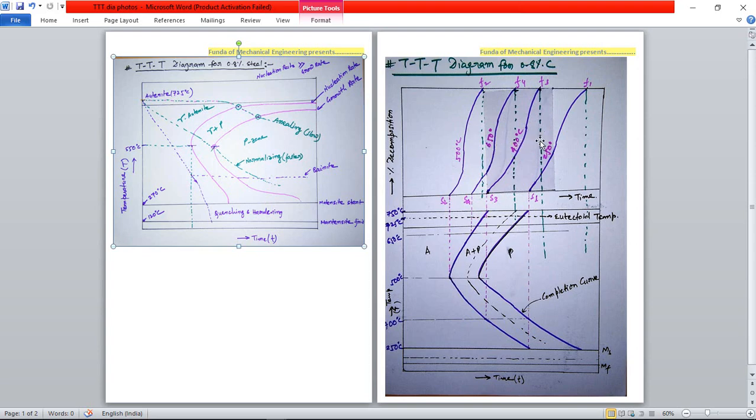Okay, no austenite decomposition is experimentally observed during a certain interval of time, S1, S2, S3, S4. This time is called the incubation period. I have already explained what the incubation period is. There will not be any transformation during such a period. That's why this time is called the incubation period, and this is the time of diffusion for decomposition. That's why this period is called incubation, because no transformation occurs at that time.